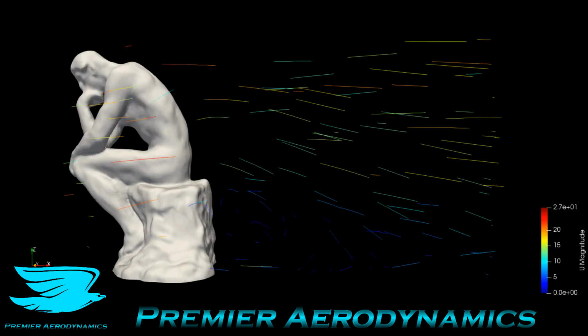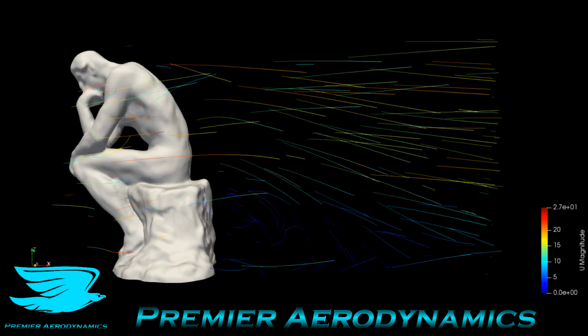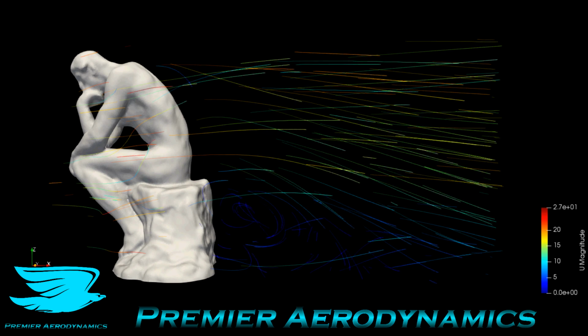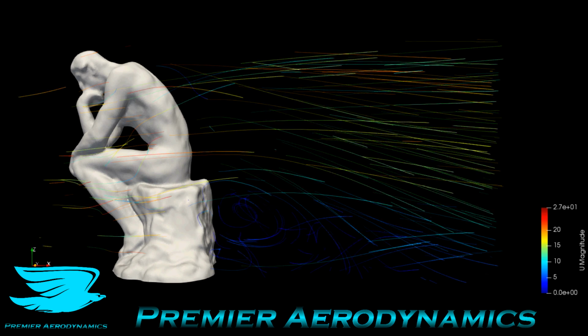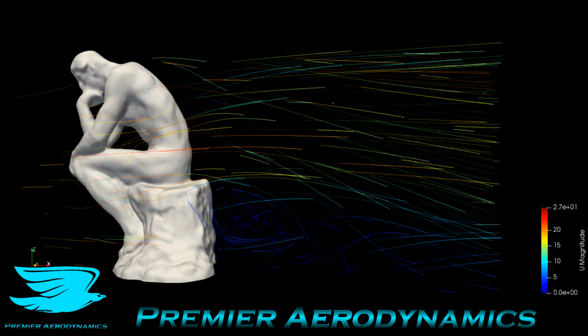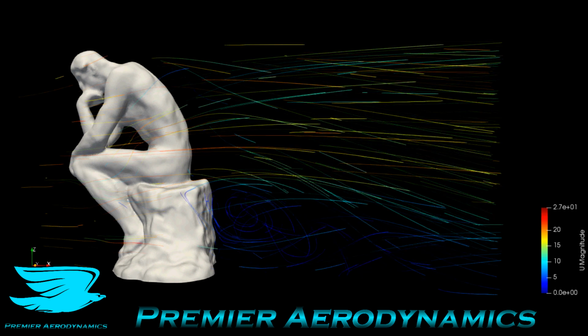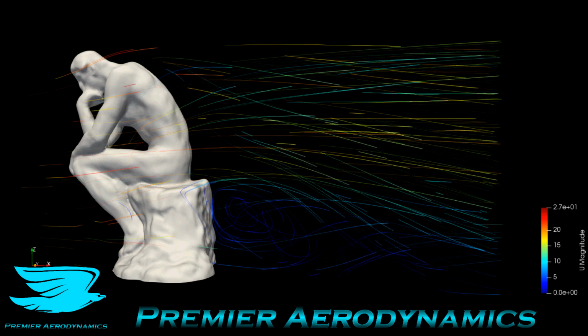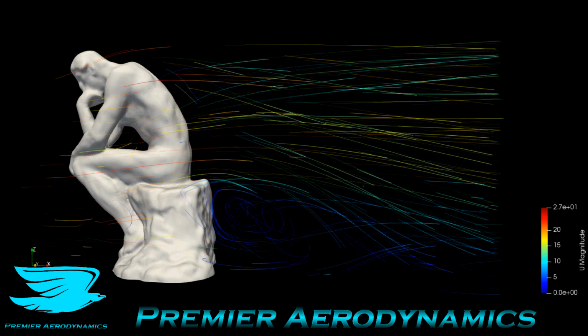And these streamlines show the animation of the fluid, and it shows a few different things that I was mentioning. First, how wakey the rock is. There's just so much recirculation behind it. It's terrible. But then the fluid that goes through the left arm hole, you can see how it just gets redirected, and there's real expansion happening. So that's in the simulation.